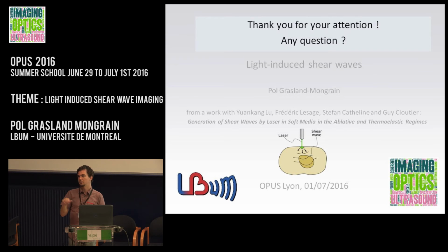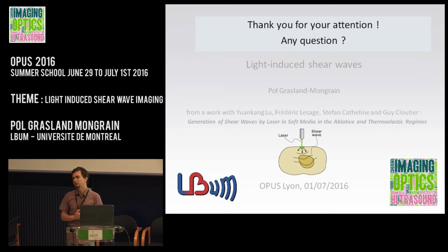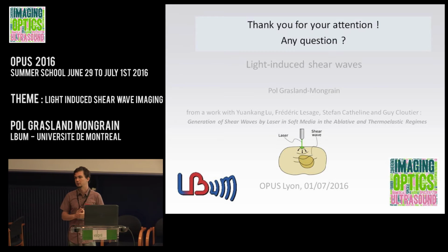It's like a digital image correlation. In fact, we interpolate the local shape, and we can see very small shapes. But in practice, for elastography, we try to have a few micrometers of displacement to have a reliable displacement.